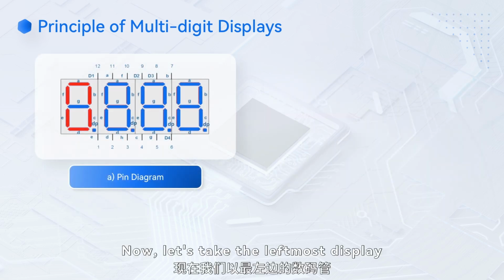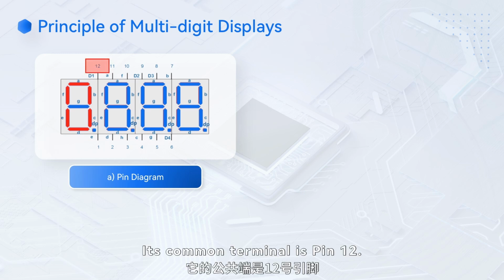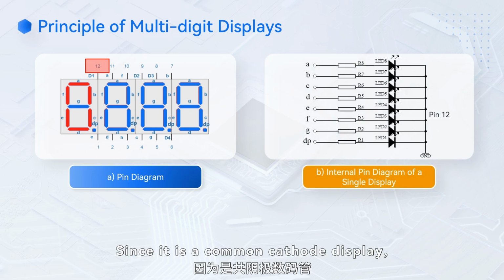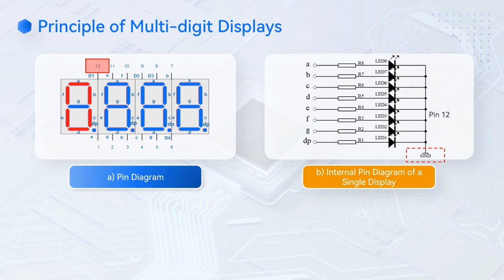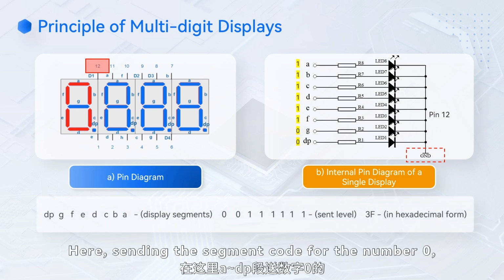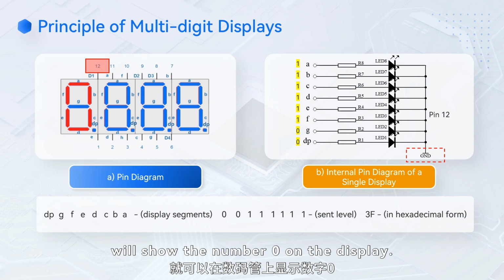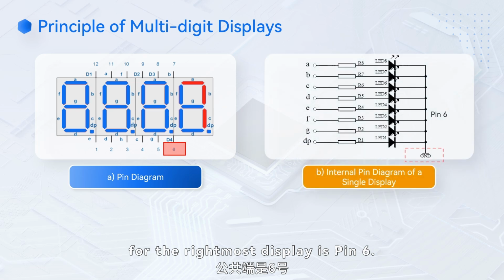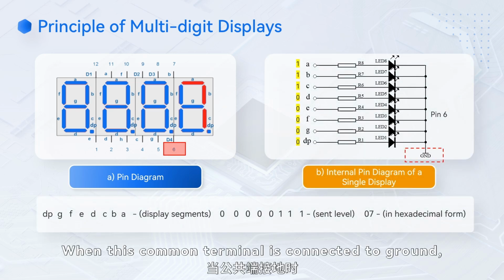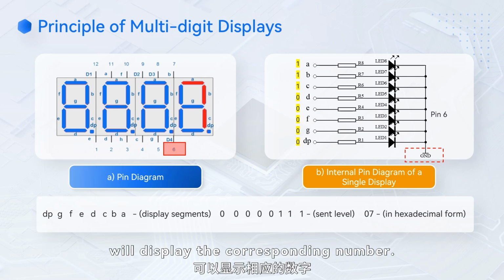Now, let's take the leftmost display as an example for explanation. Its common terminal is pin 12. Since it is a common cathode display, ground pin 12 of the 4-digit display to activate it. Here, sending the segment code for the number 0, which is 00111111 or hexadecimal 3F, will show the number 0 on the display. Similarly, the common terminal for the rightmost display is pin 6. When this common terminal is connected to ground, sending the corresponding segment code will display the corresponding number.